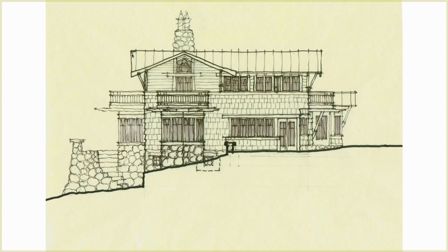The thickest line, like I talked about, is where the ground was cut through. It's this line right here. It goes right along and up and along there. That big, thick, bold line is representing where the ground is. And so we can really easily see, oh, this building is partially on a hill. There's a little bit of something going on underneath, maybe a basement or something like that. And really, that's where the hill is. Okay, I understand this building now.